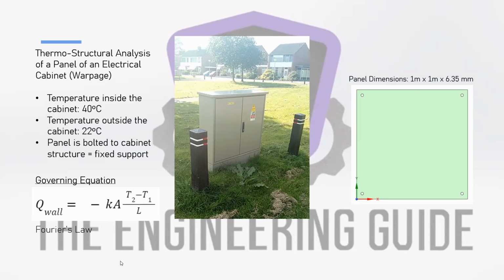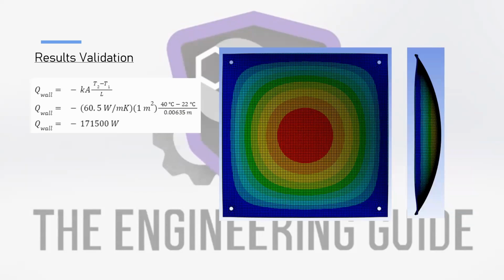And on top of these thermal loads, as indicated by the holes, the panel is going to be bolted to the structure of the cabinet. We are not going to be showing bolted connections, but we are going to resolve these as fixed supports in ANSYS to make our lives a little bit easier. And I'll talk about why we do this as we go through the simulation.